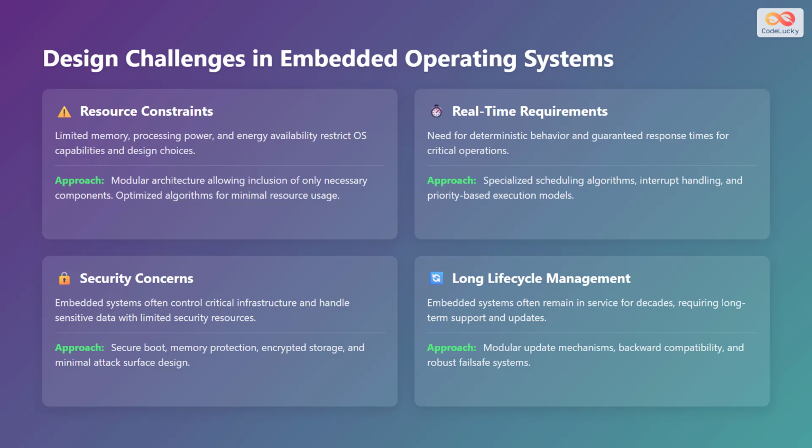Third, security concerns. Embedded systems often control critical infrastructure and handle sensitive data with limited security resources. The approach includes secure boot, memory protection, encrypted storage, and minimal attack surface design. Fourth, long lifecycle management. Embedded systems often remain in service for decades, requiring long-term support and updates. The approach includes modular update mechanisms, backward compatibility, and robust fail-safe systems.